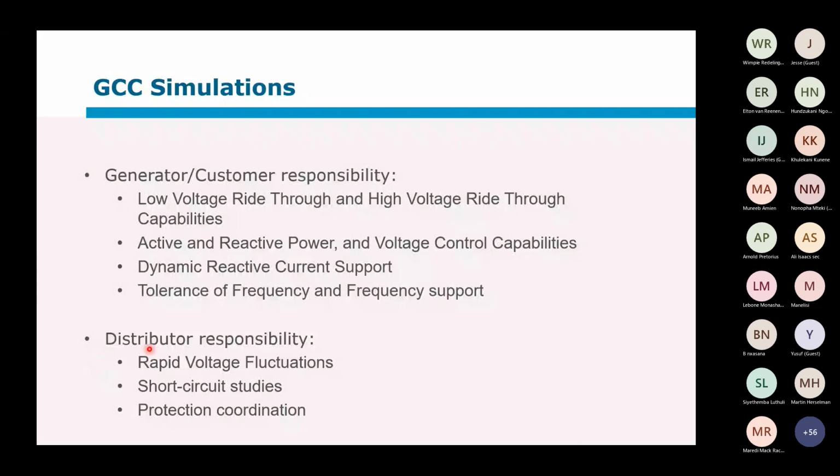Short circuit studies are required to make sure that equipment withstand capabilities are not exceeded, as well as for the protection coordination. So that's an input for protection coordination. And this protection coordination links back to a lot of that integration standard that Andrew spoke of yesterday. We've looked at the voltage ride-through. Then the voltage ride-through, at least South Africa has got a slightly better requirement in that